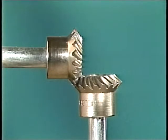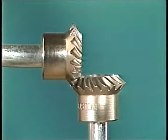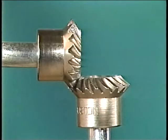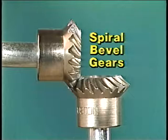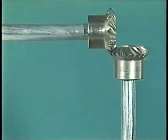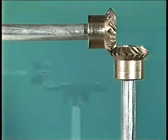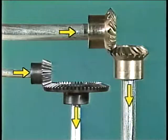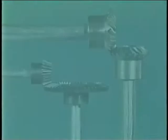Since the teeth engage gradually, the noise produced by the gear set is reduced, and since the gear teeth are twisted, more gear teeth can be meshed at the same time. This increases the load that the gear set can transmit. Bevel gears made this way are called spiral bevel gears. Although spiral bevel gears are made differently from bevel gears, the two types are both used to transfer power from one shaft to another shaft, generally at a 90-degree angle.